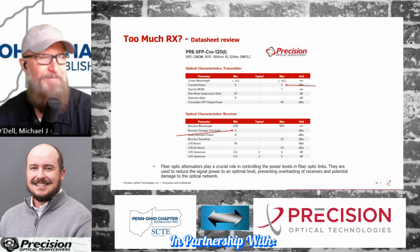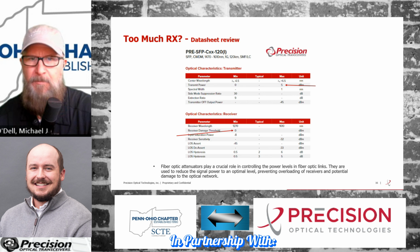And then the next step through that is the input saturation power. Because the optic could run as hot as +5, I like to tell people that you need about 13 dB of loss on this link before you can plug it in.